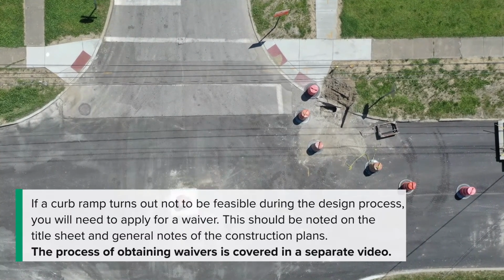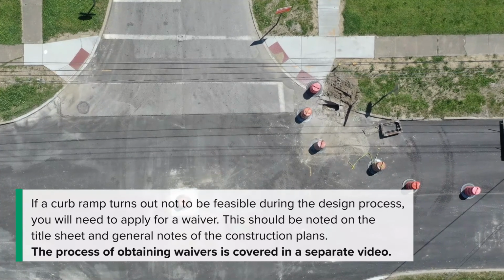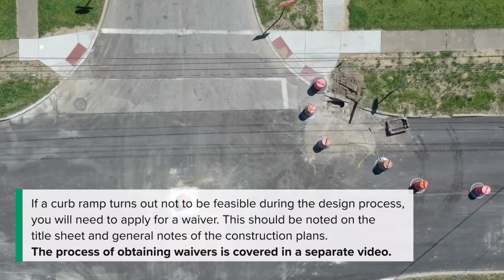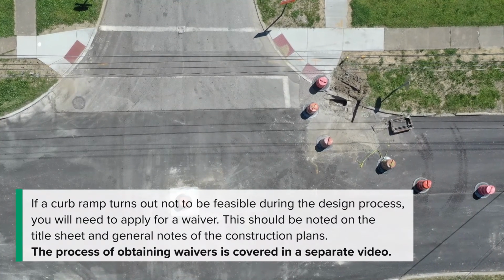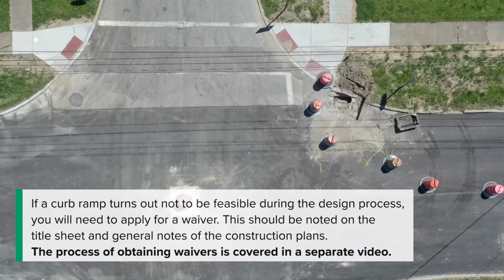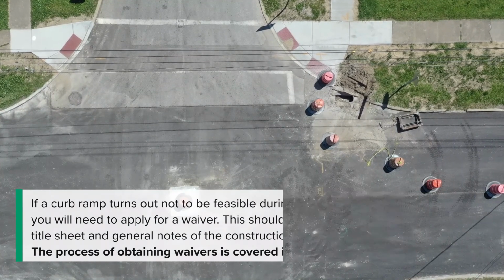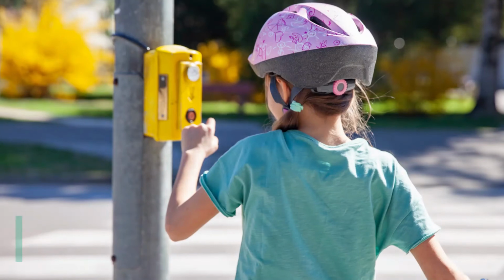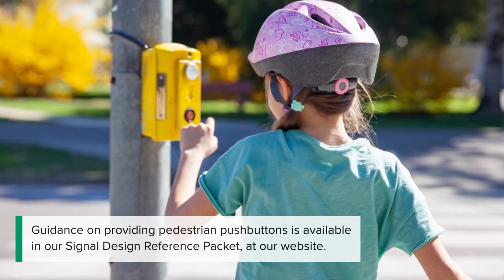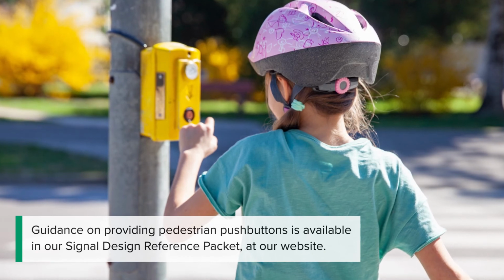If a curb ramp turns out not to be feasible during the design process, you will need to apply for a waiver. This should be noted on the title sheet and general notes of the construction plans. The process of obtaining waivers is covered in a separate video. Guidance on providing pedestrian push buttons is available in our signal design reference packet at our website.